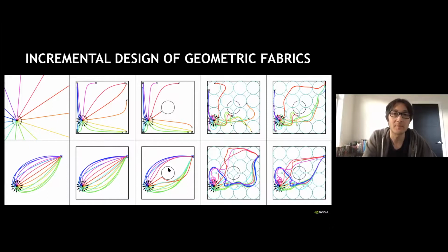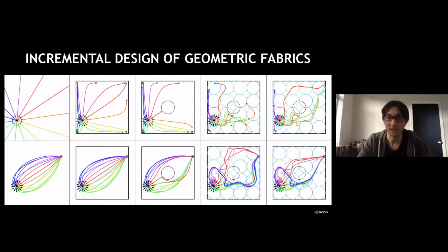And then here we've added an obstacle, and now we end up with obstacle avoidance. In this case, we're adding random vortex geometries, which is possible because we can just write down these geometries, and it's bending all over the place, but still converging to the target. And here we're shaping the behavior at the end to be a little bit more straight as it approaches the target. So it's able to be affected by these vortices and then converge to a straight line behavior at the end.